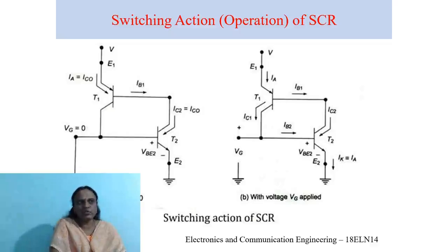The turn on time of an SCR is typically 0.1 to 1 microseconds. For high power devices, the turn on time may be much higher, like 10 to 25 microseconds. So this is the switching action of an SCR.